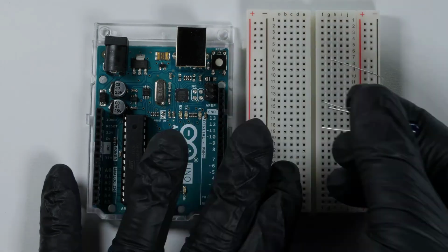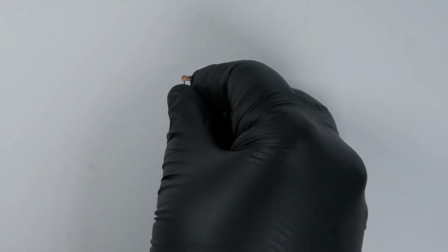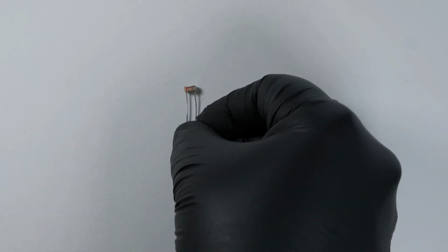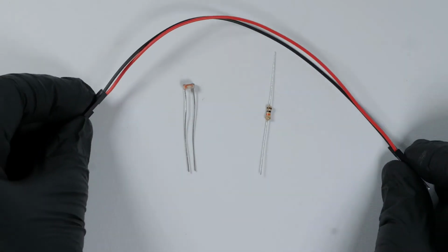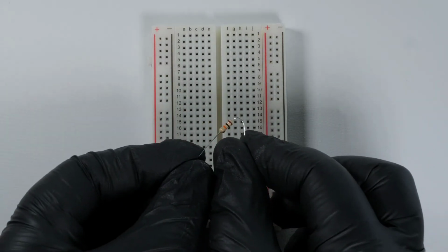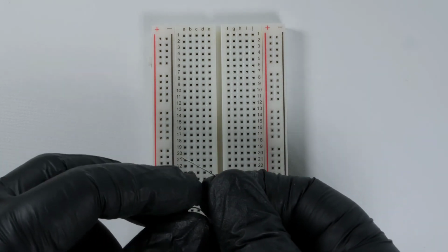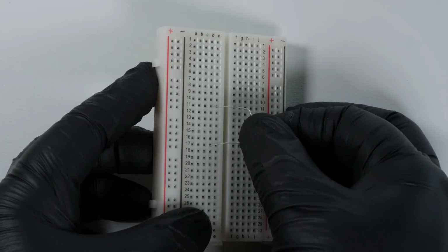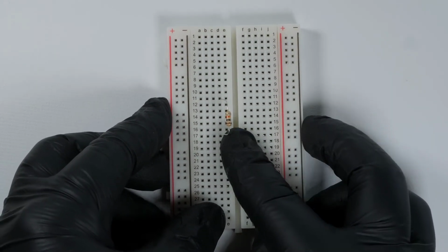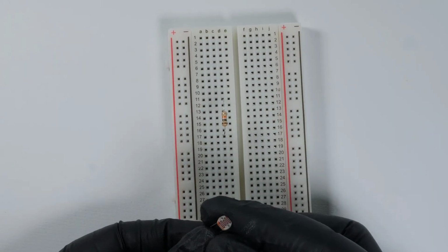The first step in building the hardware is to remove the previous circuit. Next, we need a photocell. We need a 10,000 ohm resistor to match the 10,000 ohm photocell and some jumper wires. Together with the breadboard, we can start assembling the circuit. I start by bending the leads of the resistor correctly, and placing them into separate rows on the breadboard, just like we did in the resistor LED circuit.